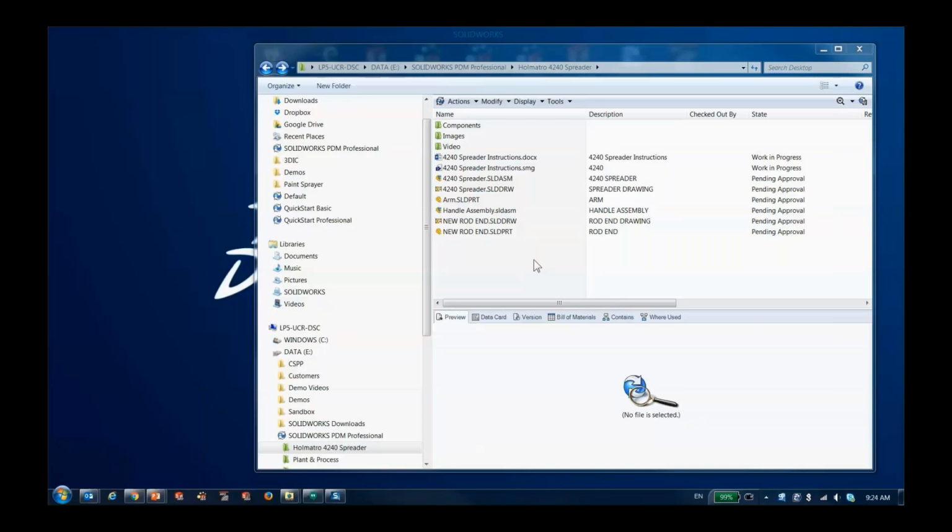Another great one is tasks. So being able to have PDM kick off a task like running a design check or creating deliverables when it's released. This is another interesting huge time suck for engineers, is every time they release drawings, oftentimes they have to create a whole deliverable package of PDFs. They have to create DXFs for a laser table or a burn table. And so these are things that we can actually automate simply by the workflow, right?